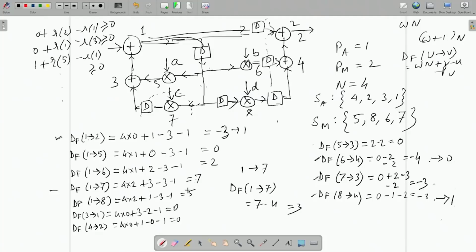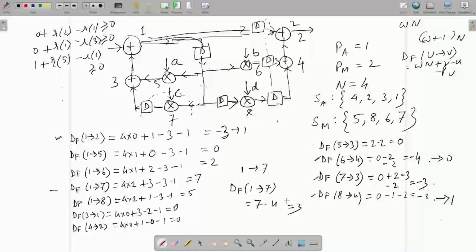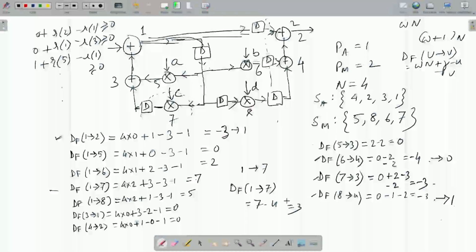But if it so happens that after you subtract 4 from the original value you get a negative, then you cannot do anything. Okay, so this needs to be checked after you complete retiming and all. You have to check wherever delay has moved from one edge to another edge. Some edge is getting extra delay, some edge is getting less delay than earlier. Whichever edge loses some delay, you have to recheck whether the folded delay value is still positive or negative. If positive, you are done. All right. This is a practical way of doing folding with retiming, that is, using cut set. But remember, you have to do this cross checking at the end also. So, that is all for this. Thank you very much.